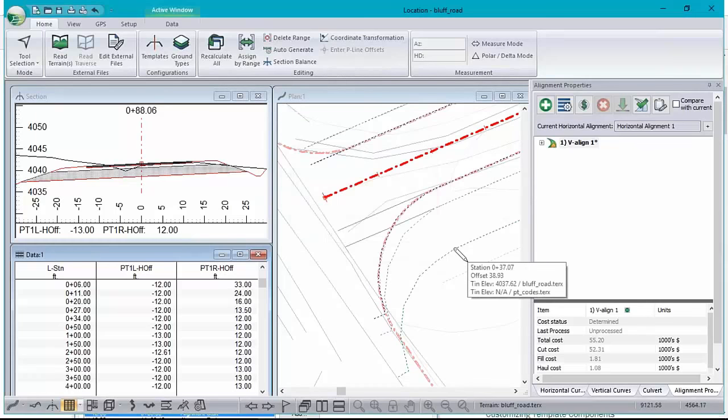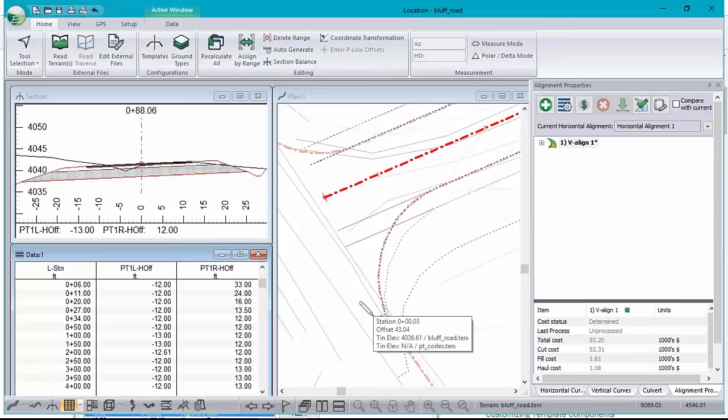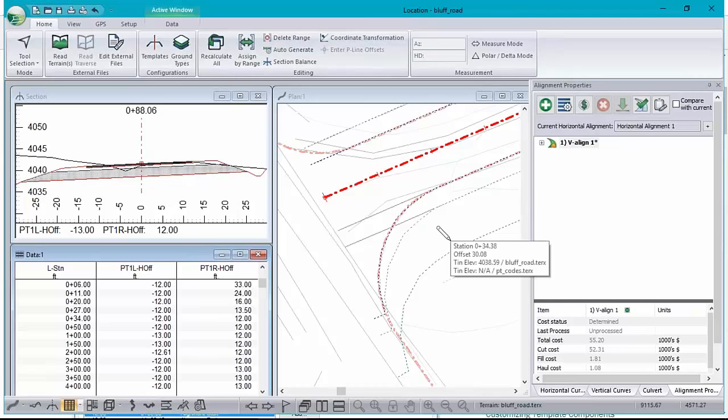But here's the drawback to intersections in road edge in general, and in this case in particular. We don't have a perfectly perpendicular intersection here. So in fact, if you go perpendicular from the start station, it starts to impinge on the existing road. And you just have to ignore that stuff. We're just working with cross sections. It is possible, if you want to get really sophisticated, to design this alignment with fill and then merge them all together in your terrain later so that you get really accurate volumes and the slope is correct.